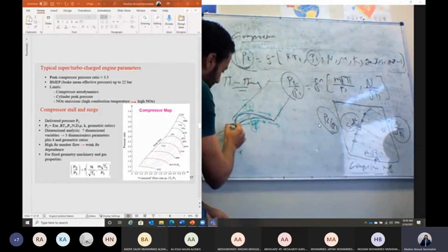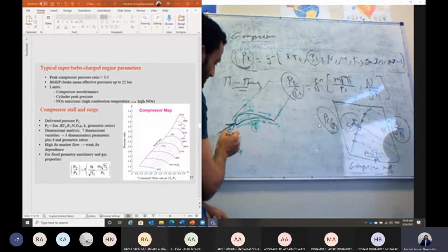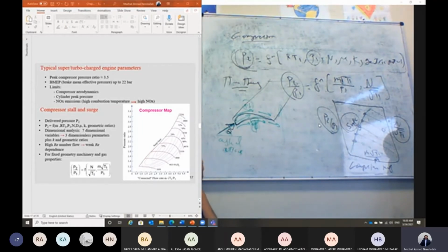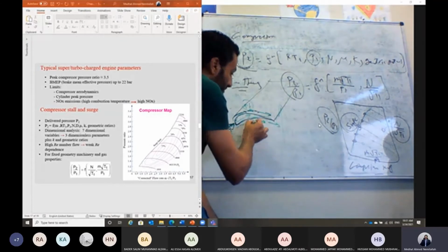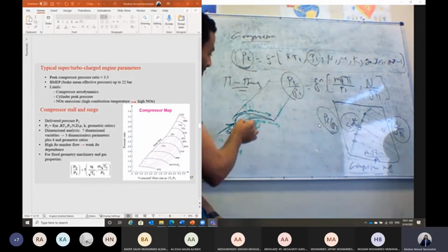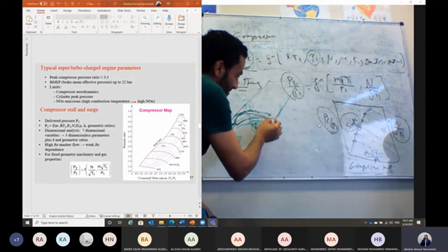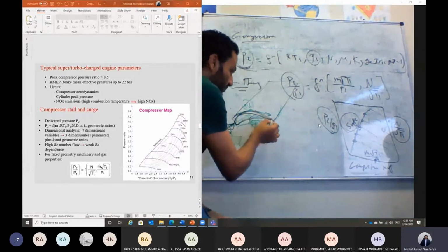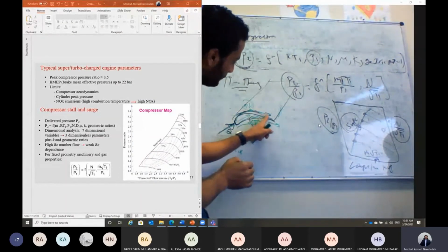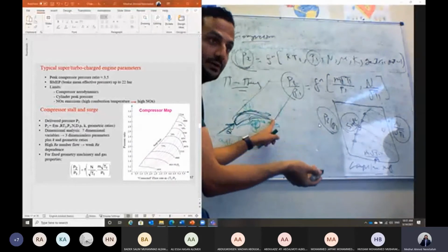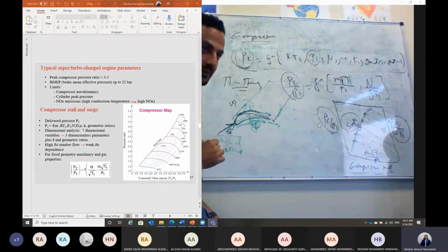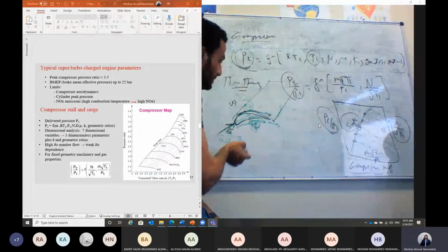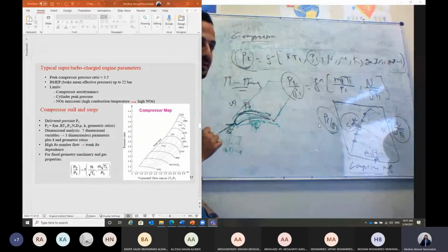So the air is coming with a given angle of attack. Let's say it is angle theta. It comes here, so the flow of air just goes in streamlines here, and it creates some pressure losses because of the distance the air should be moving. If you look at the aerofoil design, this distance is longer. So that means the air should be moving with higher velocity at the top part of the aerofoil. That means the pressure will be reduced here.